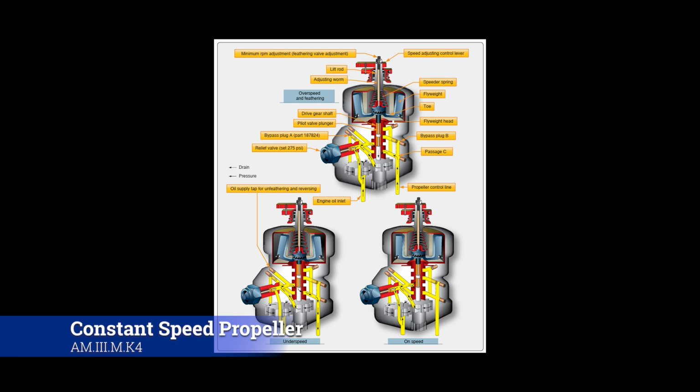And so there's two numbers there. Remember Newton's second law: force is equal to mass times acceleration. The mass of the flyweights isn't going to change. They're fixed. However, the acceleration can. So the faster they go, the bigger that force number becomes, whereas the spring tension is constant. And so that allows us to play those two against one another and get those flyweights in a certain position. As those flyweights change position, it also helps change the blade's pitch.